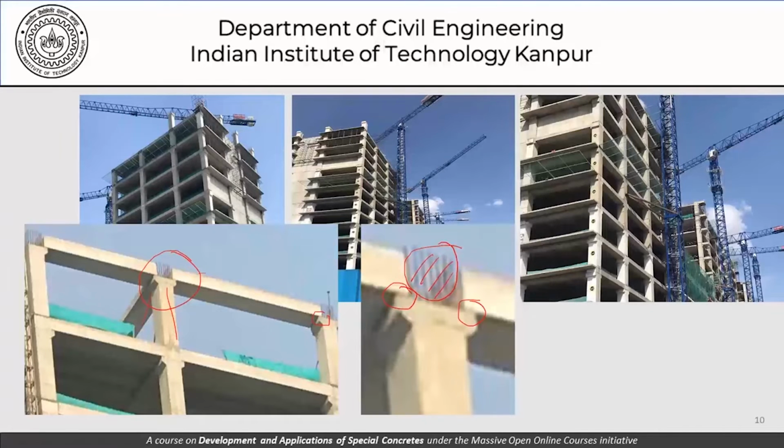These members are still reasonably vulnerable to displacements, and that sometimes becomes the cause for accidents when these precast members are placed in position but not securely fastened. So there have to be arrangements made for temporary fastening of these members while the permanent steps to be taken as part of the overall construction are done later on.